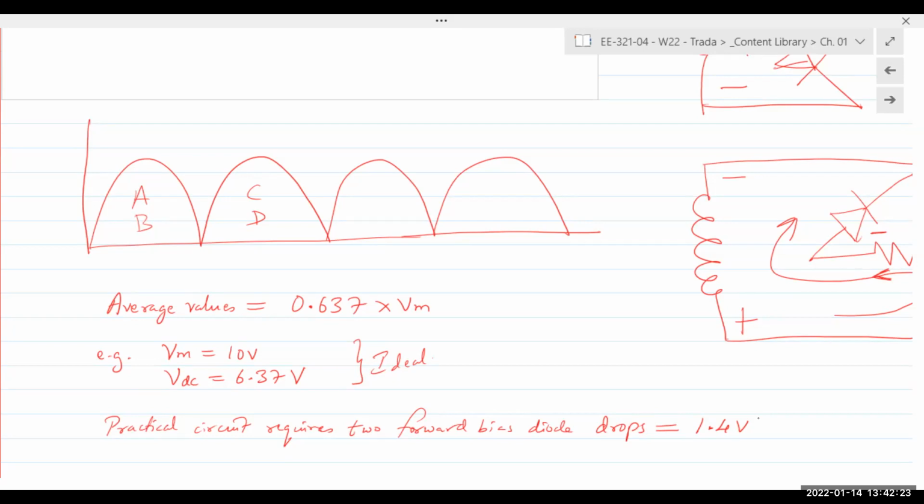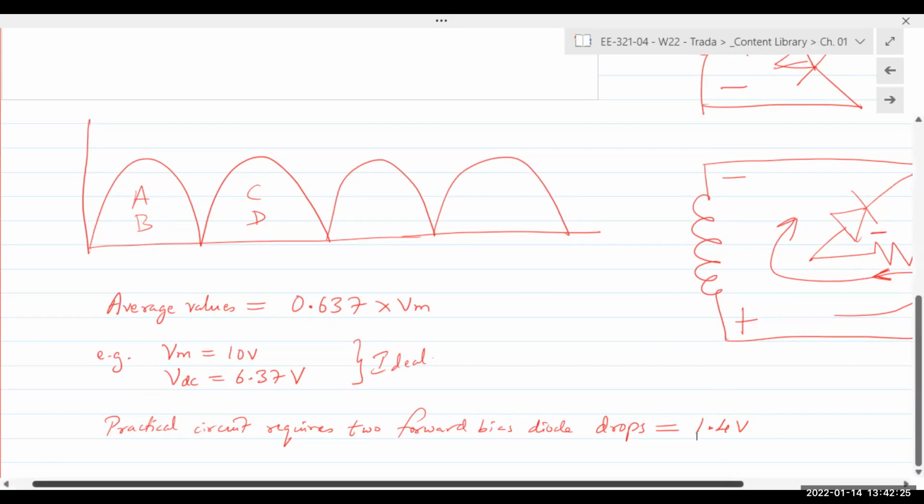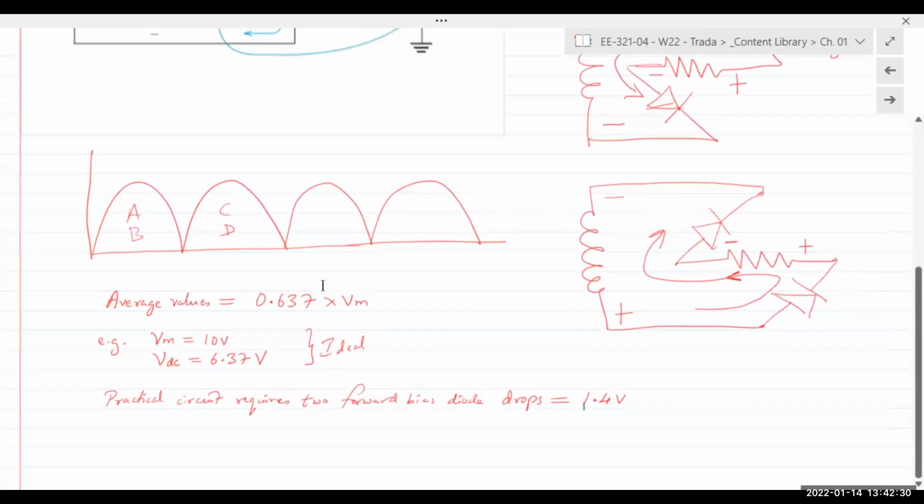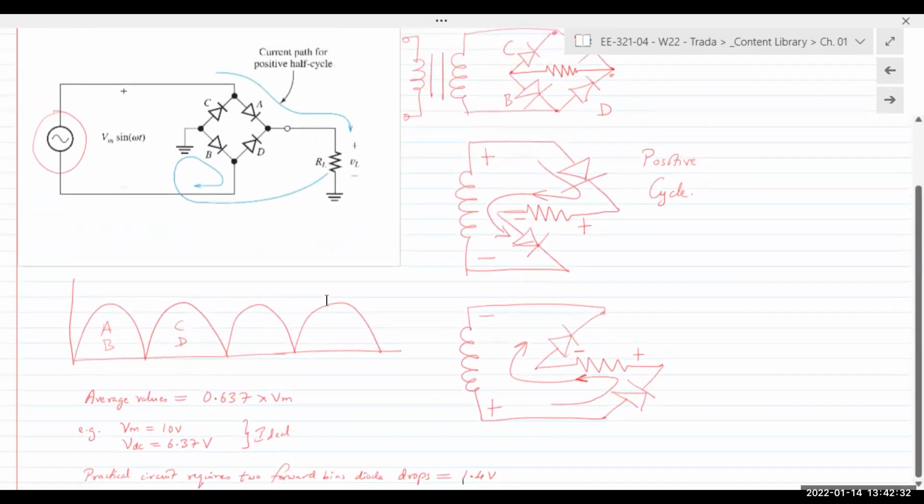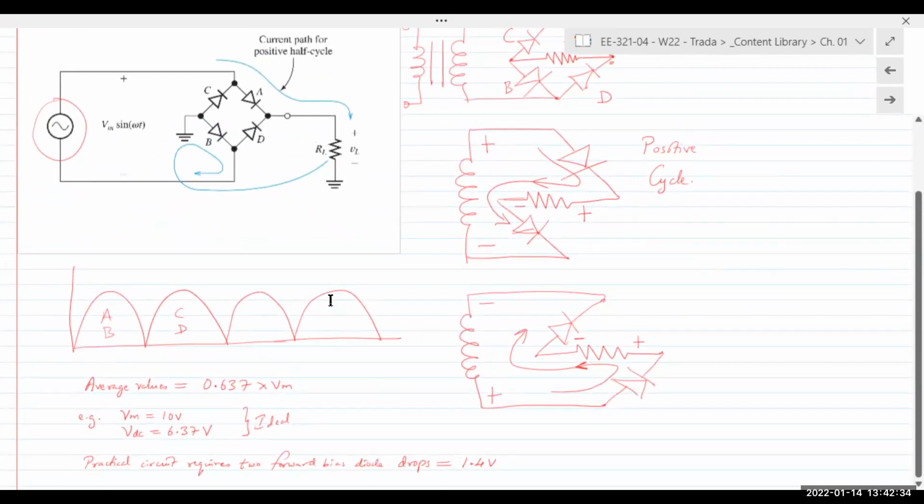But before we move on to that, any questions? Yes, absolutely. So it'll be somewhere around 5 volts or less. Now, the other consideration is that we would have filtering circuits as well as voltage regulation circuits, and that would require that you have the voltage slightly above that for the voltage regulator and filtering circuits.